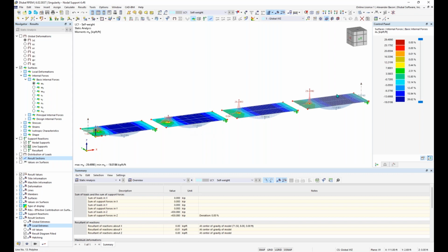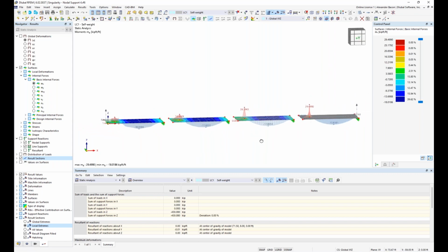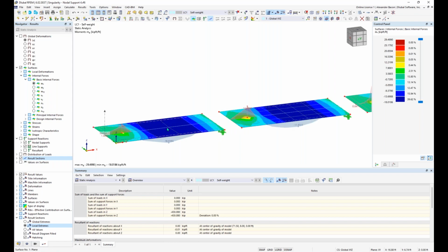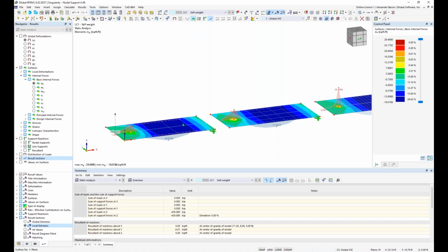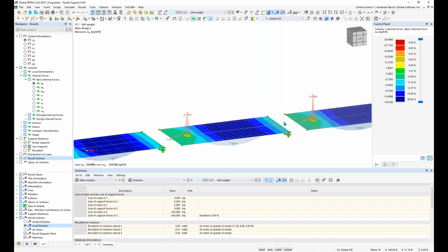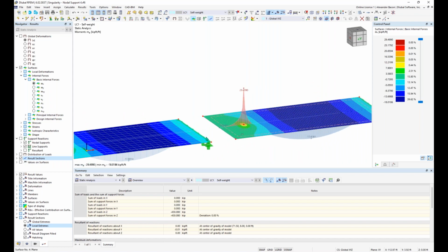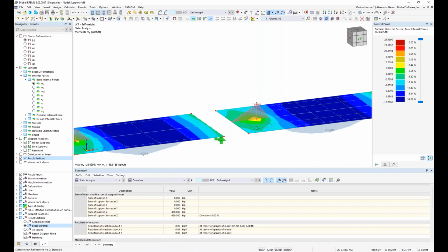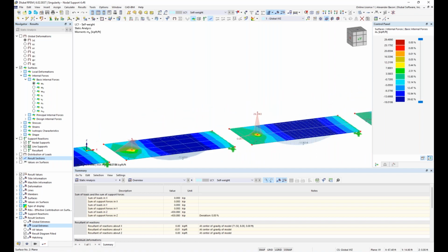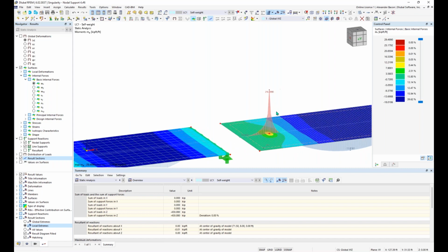So these are not results you can rely on, and the correct result out of all of these surfaces is none of them. None of these are correct, and it doesn't matter what your FE mesh looks like. But like I mentioned before in the PowerPoint, having a finer FE mesh doesn't fix singularities, but it does, as you can see, give you a better idea of where that singularity is exactly located. As with this, you have no real clue where that singularity is happening. You just have a better idea with this finer mesh here.